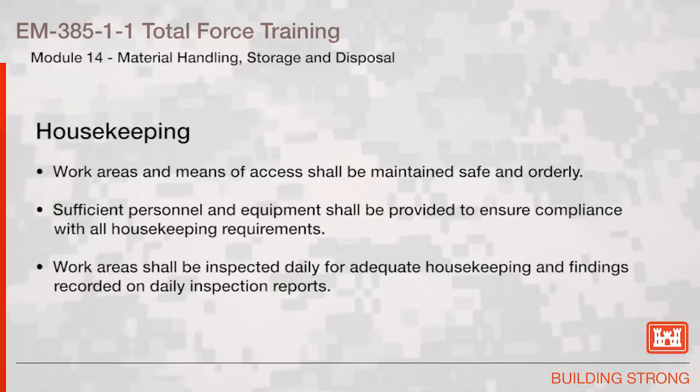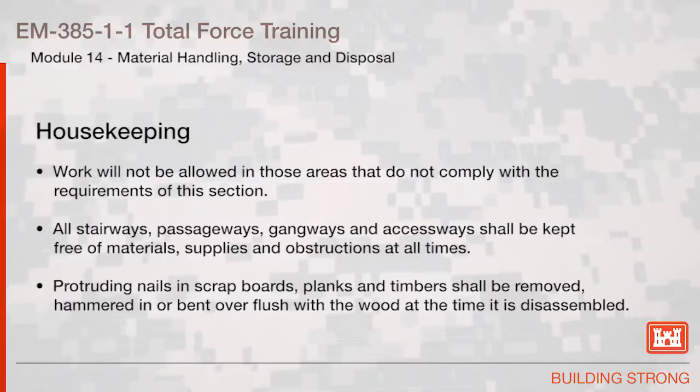Work areas and means of access shall be maintained safe and orderly. Sufficient personnel and equipment shall be provided to ensure compliance with all housekeeping requirements. Work areas shall be inspected daily for adequate housekeeping and findings recorded on daily inspection reports. Work will not be allowed in those areas that do not comply with the requirements of this section.